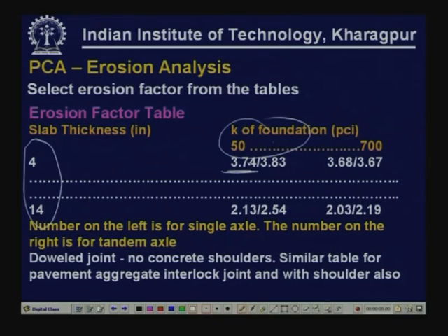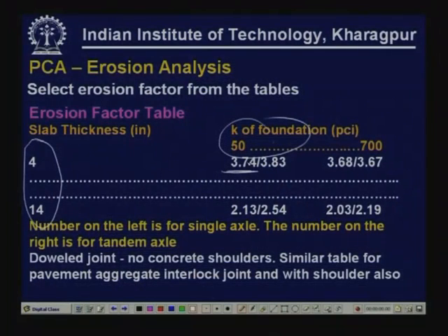You can see the tandem axle factors are larger than the values given for single axle, whereas in the case of stresses, the stress factors are more for single axle compared to the tandem axles. Here also we have tables available for different types of shoulders.